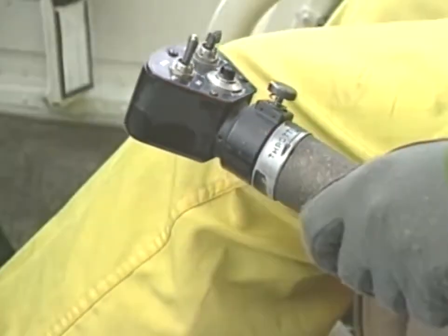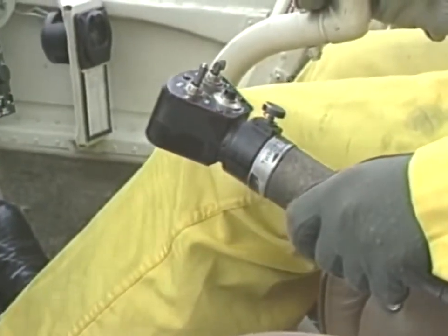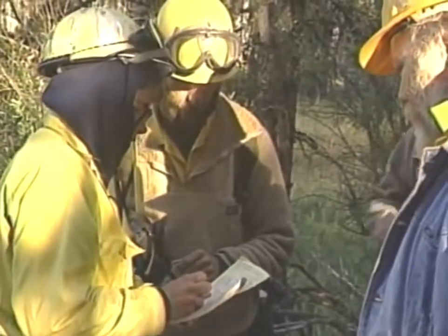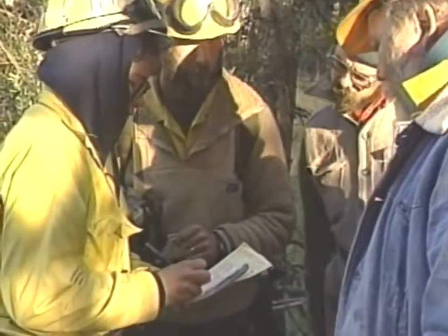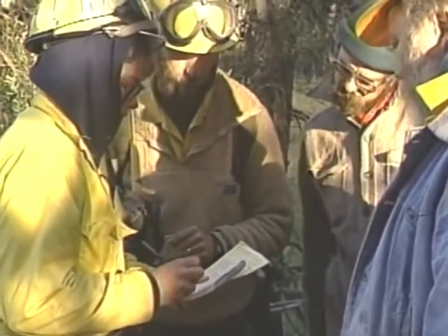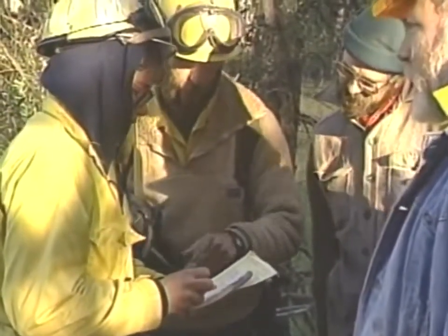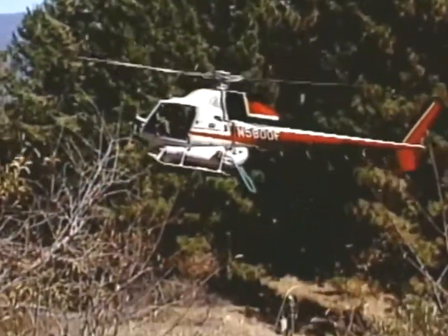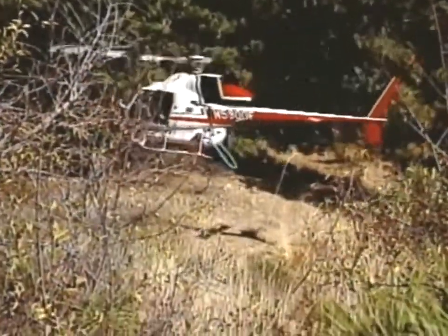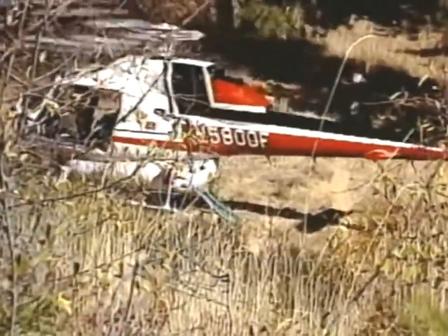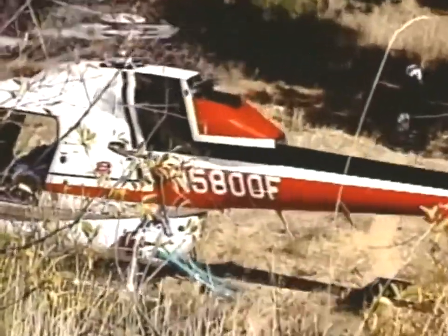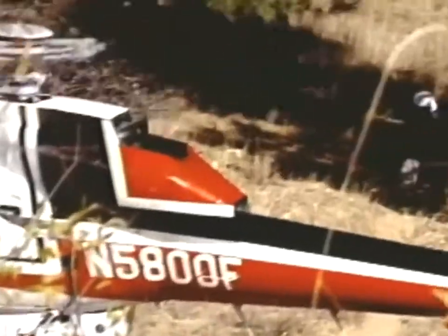Helicopter performance and capabilities decrease. So, during the warm summer months, plan your helicopter projects for early morning when the air is cool to maximize the performance of your helicopter. And when you add hover out of ground effect landings, or HOGE, to your project, just remember the saying: when it's high, HOGE, and hot, you may not carry a heck of a lot.